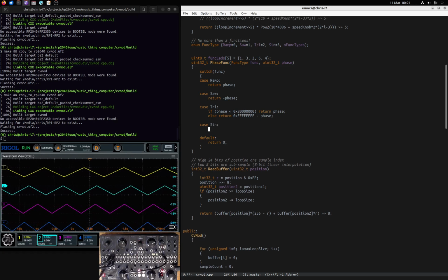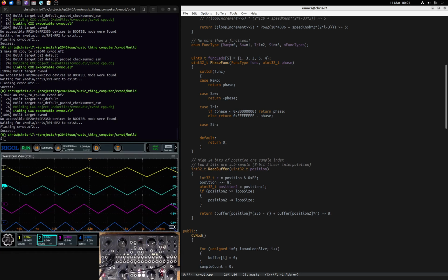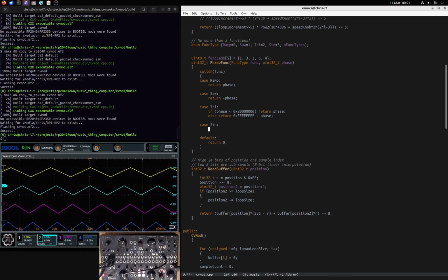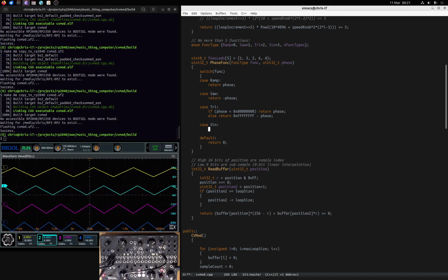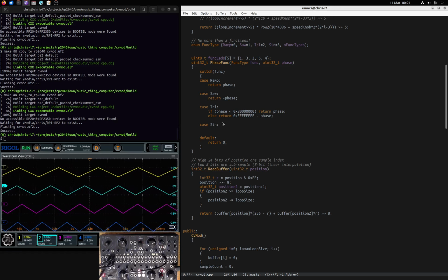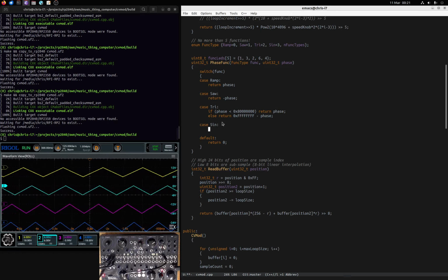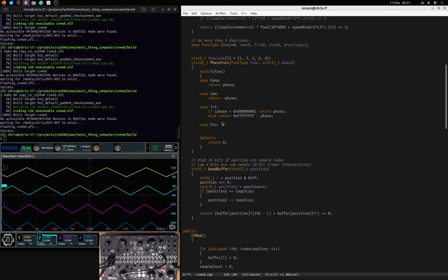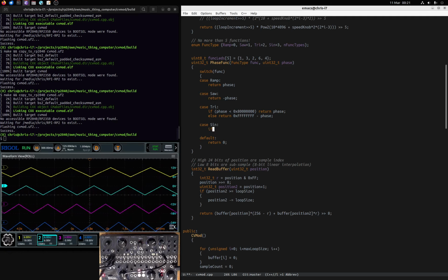So this isn't really a sine wave. Again, this is a case where there's sort of two options here. We could make a lookup table for sine, or we could just generate a parabolic approximation, and I think I'm going to do the latter for now at least. So a parabolic approximation for sine is going to involve, I think, 4 regions.